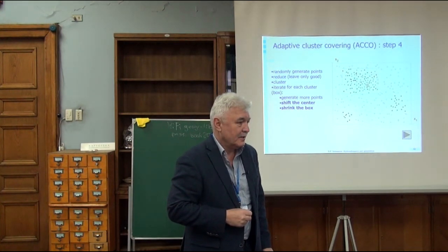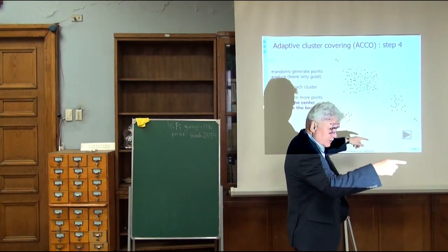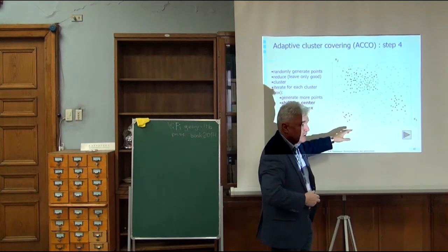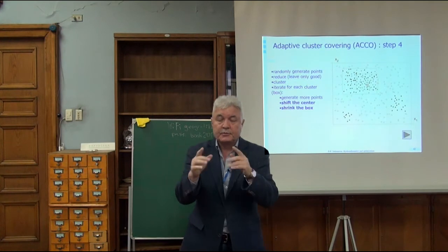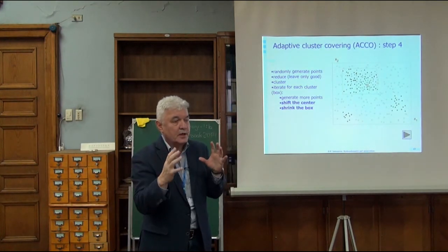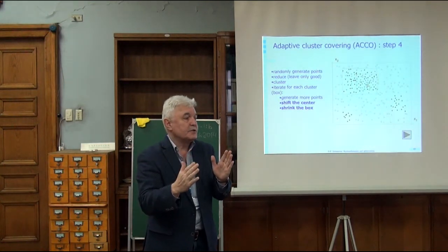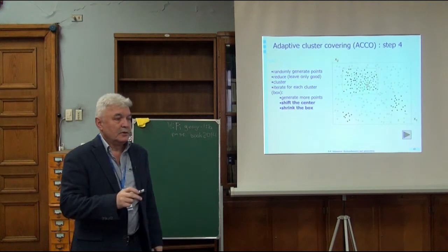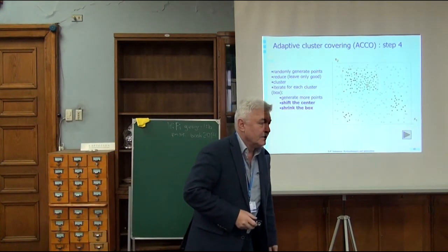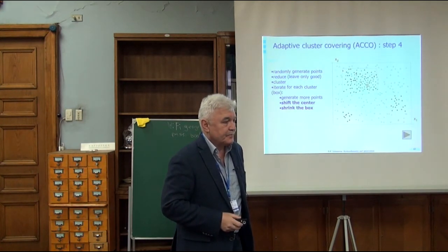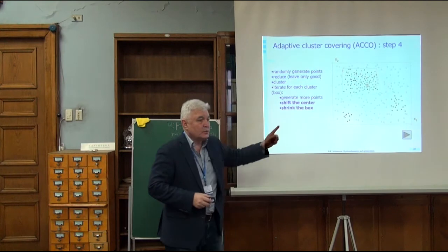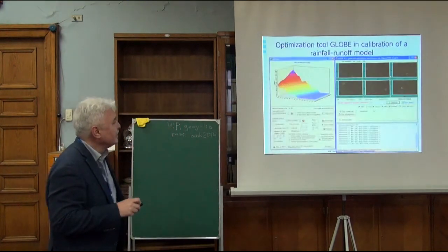Do you use parameter limits also? These are parameters, x1, x2. If we calibrate a hydrological model, these are the model parameters. Yes, of course. This is constrained optimization. We impose limits, ranges, for the parameters to optimize. We do this in a hyperbox, a hypercube, in which the ranges for the parameters are physically based, of course. If we talk about calibration of models, sure. So it's not a blind search. If we use a black box model, we have the opportunity to impose some limits on parameters. When we talk about model calibration, I will speak about this.